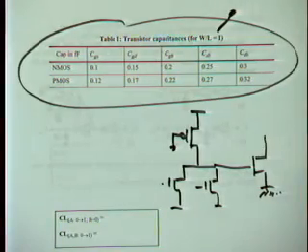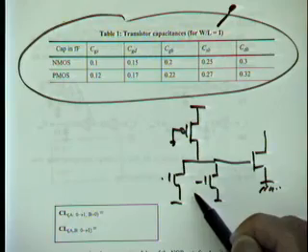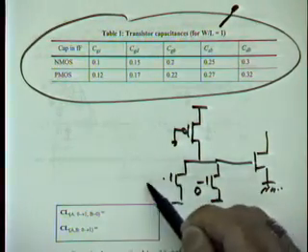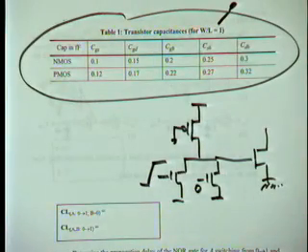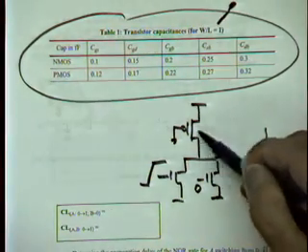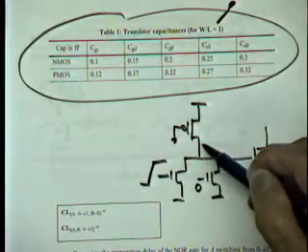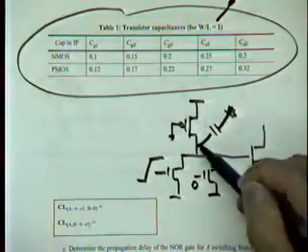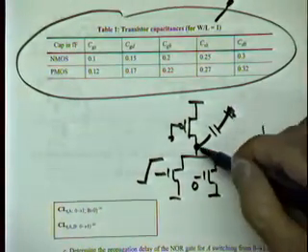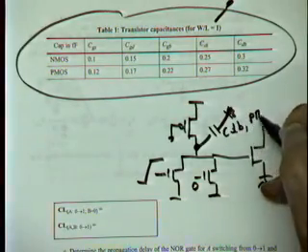Okay. So let's look at the case where B is fixed at 0. It's off. And we move A from 0 to 1. Okay, so what's going to happen with my capacitor? What capacitance do I have to take into account? First of all, if you look at the PMOS transistor, what's the PMOS going to provide? PMOS is going to add me a capacitance from drain to bulk, so the CDB of the PMOS.